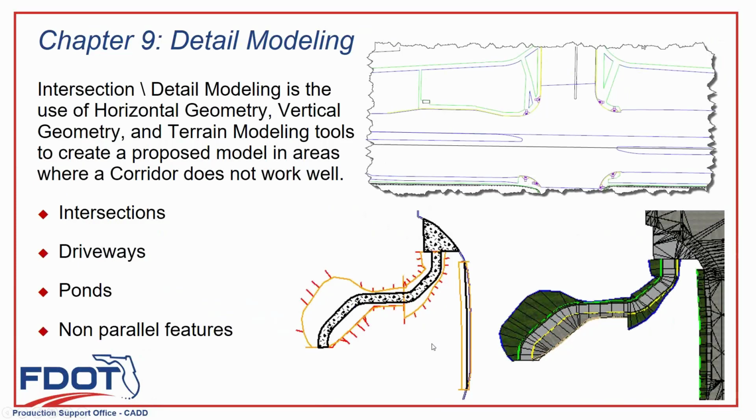So let's just have a Q&A, and I'll do some demonstrations on how to detail models and this other stuff. And it's going to be the same techniques with a little twist, maybe. And you know, after a while, you're going to see that the approach is pretty much the same. You lay out horizontal lines, you create profiles, you create terrains, you use linear templates on the edges, you clip, or not clip.